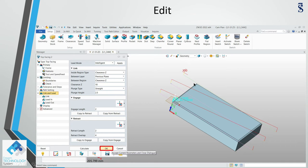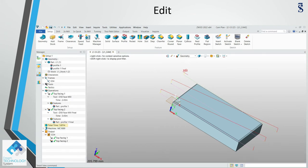Anyway, this is how we go about it, and then we calculate this, and we can see that the tool path is actually one direction, going all the way back, and then we go through again, 3 times, so that the tool path is correct on 3 locations. So we click OK, and we can see the cycle time is reduced over here, and now the total cycle time is 5.87. So that is already improved from the 9 minutes at the start.